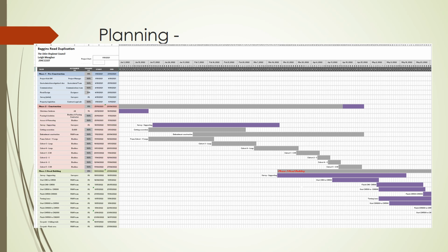The next slide we're seeing here shows the interdependency of the timings. The upper section shows the critical steps being the cutting, excavation, and the culvert installations. Chainages 1500 to 2000 and a portion of 1000 to 1500 have the potential to be built in advance of the lower chainages, as do the car parking accesses and the car parks themselves. Thus, if we do hit blockages, we can then keep production going on the project by moving to those lower priority tasks.